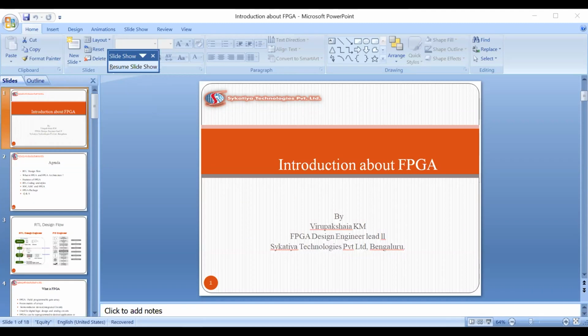And size also matters very much, because in the PCB you are designing with very little size, and the whole size will be taken by the FPGA. Where will we fabricate or solve other boards and other applications like 7-segment, microcontroller, flash, buzzer, other ports, which you also have to make on your PCB boards, right? So the size of our FPGA also matters. And the package, I will explain later how to select our FPGAs. So these are the selection criteria of FPGAs for your successful design or project.